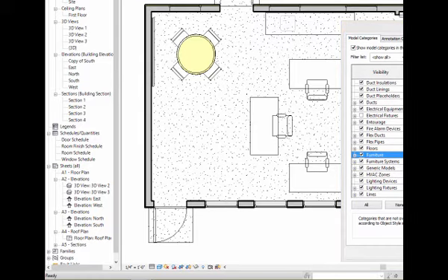So the line choices are, we can change the weight of the lines. It goes everywhere, and this is a relative scale from 1, which is a very skinny line, to 3, which is kind of an average thickness. 5 is a standard size that I tend to use for wall thicknesses. 7 is getting pretty heavy. 9 is getting very thick. 11 is getting ultra thick. All the way up to 16. So depending on what you want, you can bring them up quite a bit higher. I'm going to choose to show my furniture outlines in 7, so a heavier line weight.